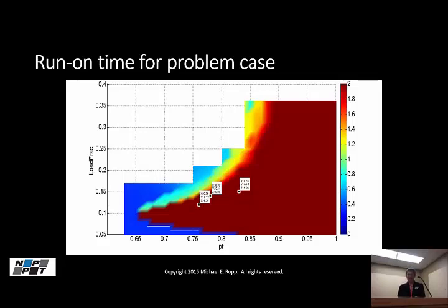The thing is, the way the standards are worded right now, it is the responsibility of the distributed generator to detect and prevent that condition. So you can't rely on the load. If there is a case where you couldn't see the island, then the distributed generator has failed in its job. And of course, it becomes a risk mitigation issue too. Obviously, you can't reduce the risk to 0, right? There was a risk involved in walking down the hall from the cafeteria back to this room. So I'm not sure what it was, but there probably was one. So we have to be reasonable about this, is the point that I'm trying to make.